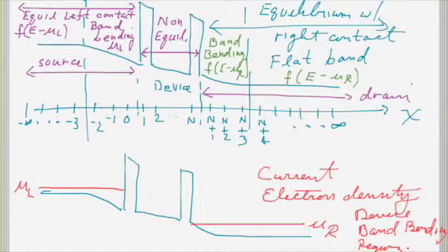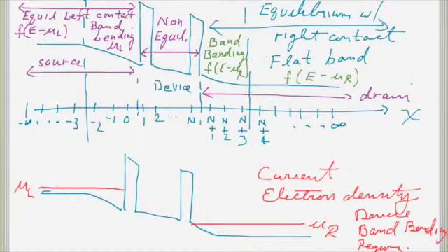So we're going to start on the right-hand side by calculating the surface green function of the semi-infinite right lead. The semi-infinite part is the part in flat band. After the band bending, all the flat band, the semi-infinite region that has no potential variation.